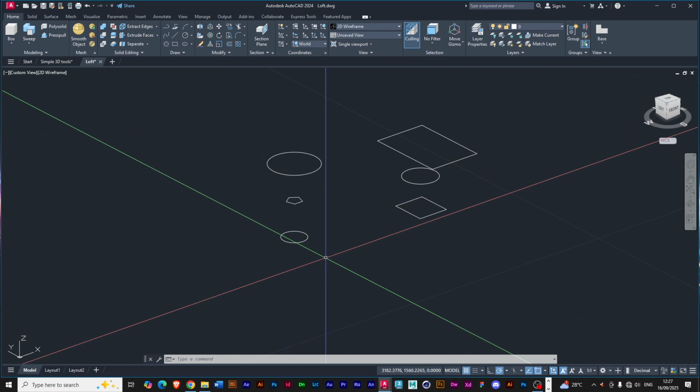Imagine you had a Coke bottle and you wanted to draw the profile of the Coke bottle. Like how we did last time, you use your pencil and sketch out the profile of the bottle. Now with a loft, you can just create circles and place them at key points of the curves of the bottle, and loft will generate a surface from the first to the last.